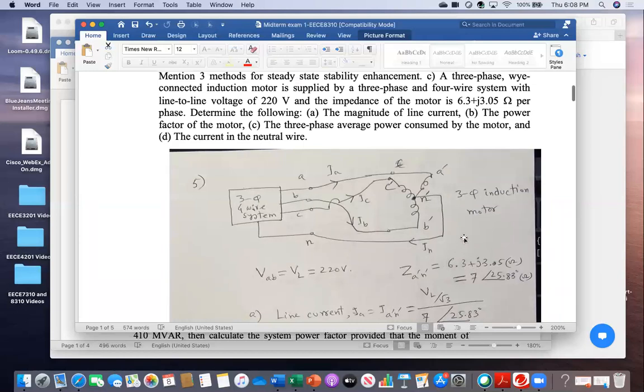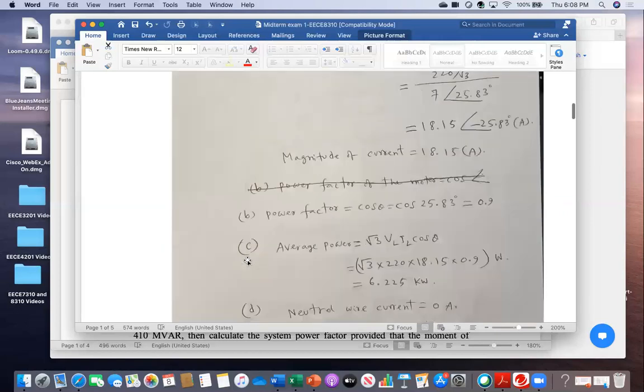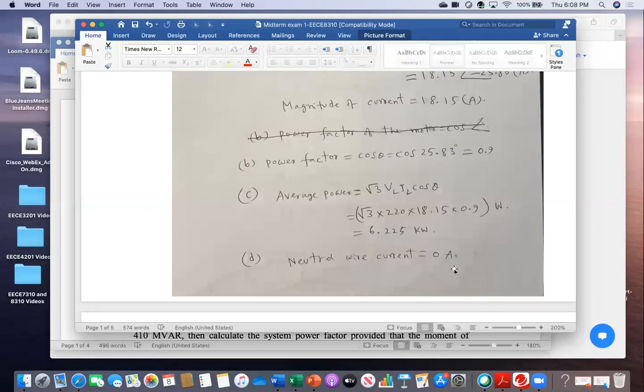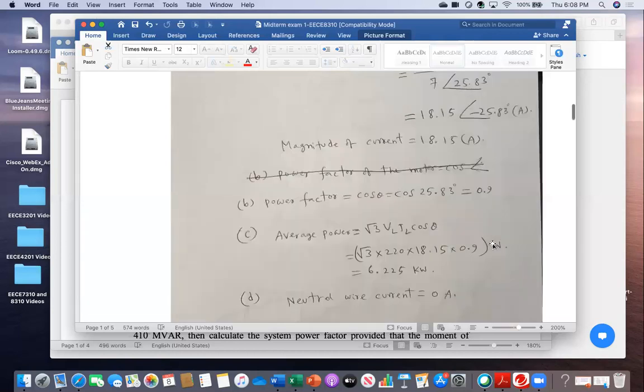Oh, I missed this one. You did not answer this one? No, I answered, but I just added all those three phase currents. You can sum up the three currents, but the result should be 0. There should be a vectorial summation. Maybe somewhere you made a mistake in the calculation. I just put the algebraic sum, so that's the mistake I made. I did not show the calculation because I assumed you all know. Straightforward, I wrote 0 because it is a balanced system.